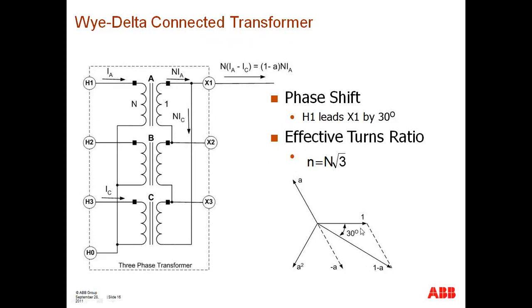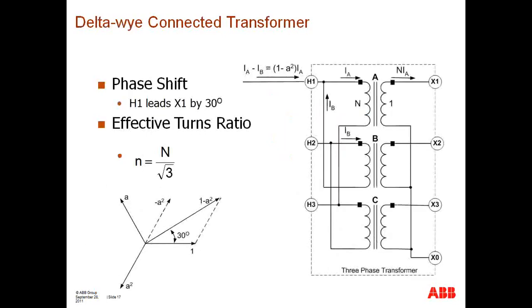And then the delta connection is utilized on the generator side so that, again, we provide isolation between the zero sequence networks, in such a way that if a phase-to-ground fault occurs within the generation station, the transmission network does not become a source. This is a decision that's made because, as we've discussed on other webinars in this series, most of the faults are phase-to-ground faults.